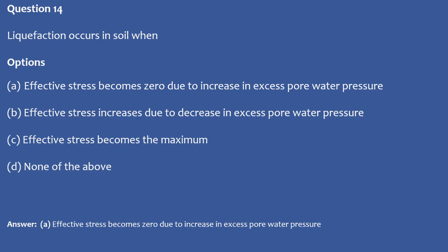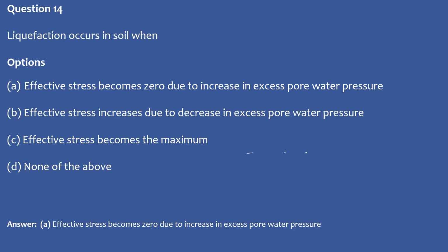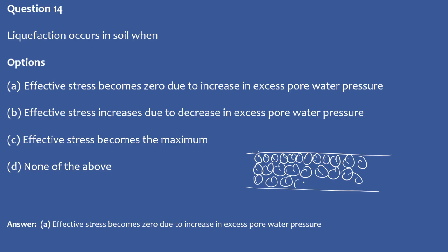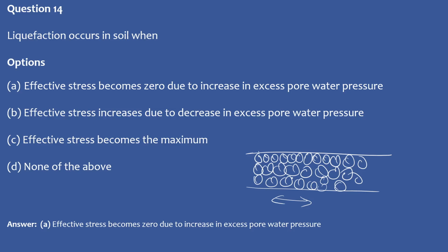The effective stress basically becomes zero due to the increase in the excess pore water pressure. So let's say you have a certain soil matrix of cohesionless soil type, and this is fully saturated, meaning all the voids are filled with water. Now let's say I shake or vibrate this soil matrix.